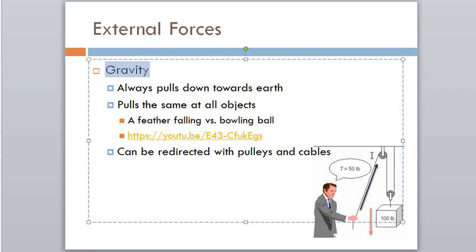And when I grab this cable and I pull it, although the force is pulling my arm up, so I have to pull down, the result of this movement is that weight goes up, so I'm overcoming gravity. So just be aware that machines that have an axis or a lever, like fixed plate type machines with a selector plate, or pulley stacks, high and low pulleys, they're still under the effects of gravity. The weight, the resistance, is still under the effect of gravity. It's just that the cables redirect and redistribute forces.